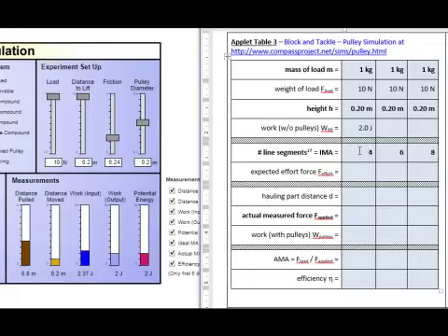Okay. The ideal mechanical advantage in a pulley system is really easy to determine. Just count the number of line segments that are supporting the weight. There were 4, so the ideal mechanical advantage is 4. That should cut down the expected effort force to 1/4 of the original. So as I'm trying to lift a load that has 10 newtons, I should be able to apply just 1/4 of that, so 2.5 newtons. That's what my spring scale should read. However, there's friction, so it won't read that.